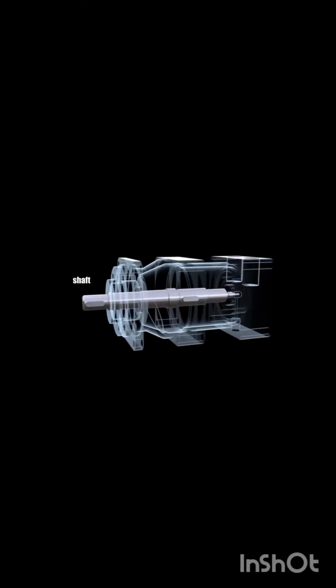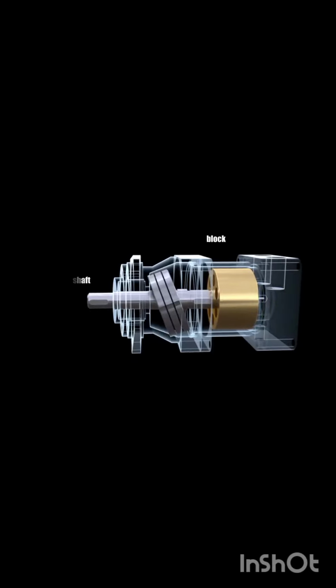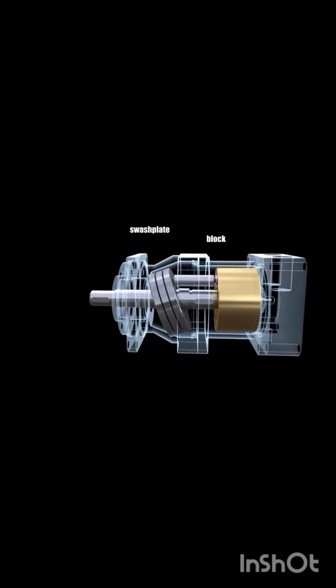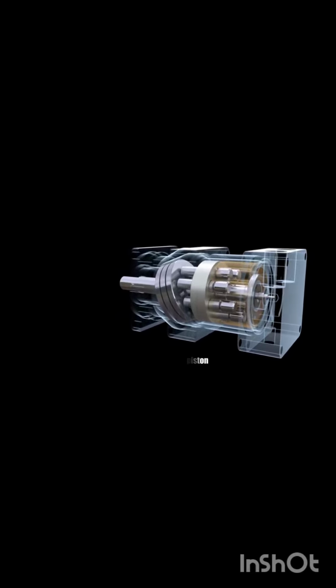The cylinder block of swash plate pumps is installed coaxially with the drive shaft, and the rotation is usually transmitted to the block using a key or spline connection. The pistons rest on a swash plate supported by special pushers that have a spherical surface. The cylinder block is installed on a valve plate connected to a rear